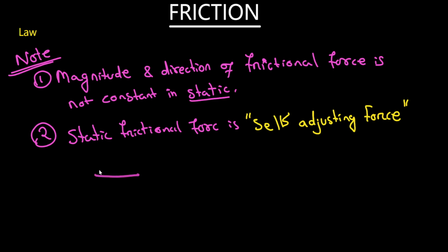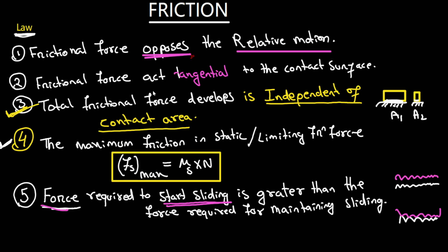One force was the force in the direction of possible motion, that is P, or whatever the component of the force along the contact surface. The motion will happen in the direction of that force only. He's saying the frictional force will oppose the motion. Suppose motion is in the x direction, so the force acting in the possible direction is in the x direction. The friction is also tangential to that force. We have seen in the statement that the frictional force acts tangential to the contact surface. The force in the direction of possible motion is also tangential.